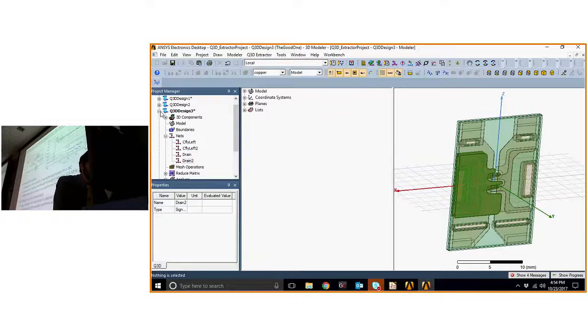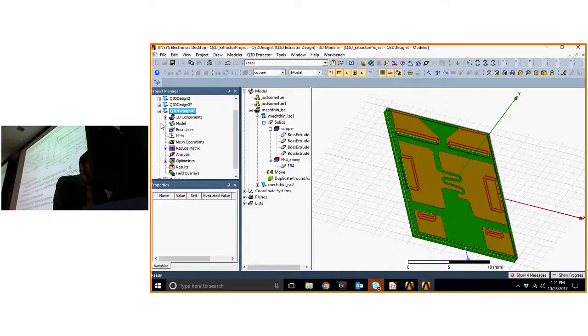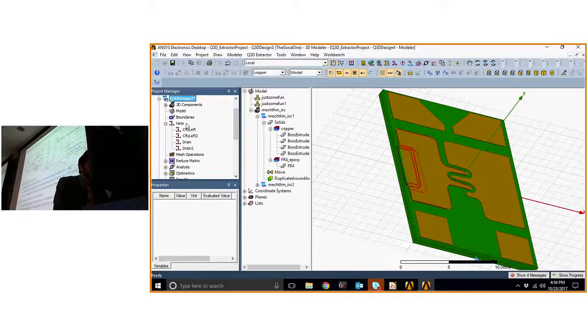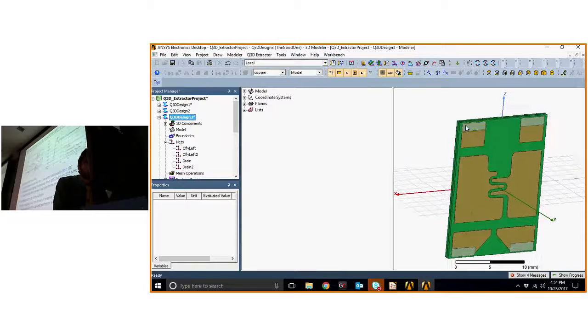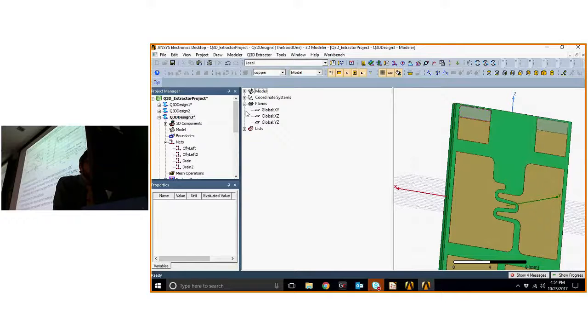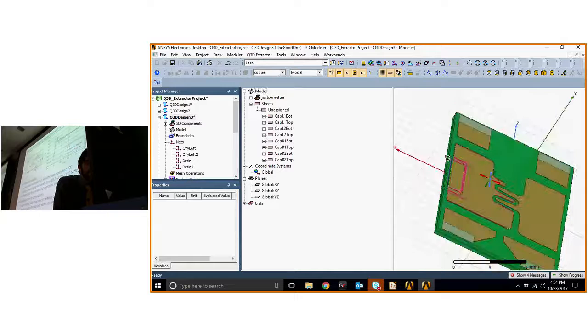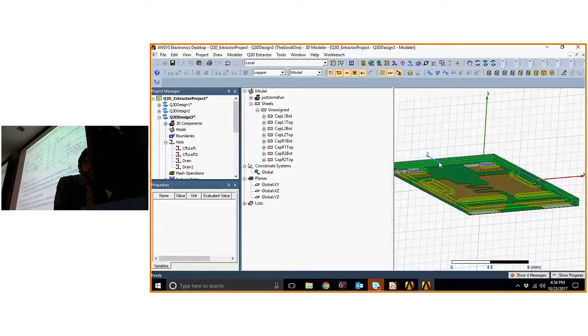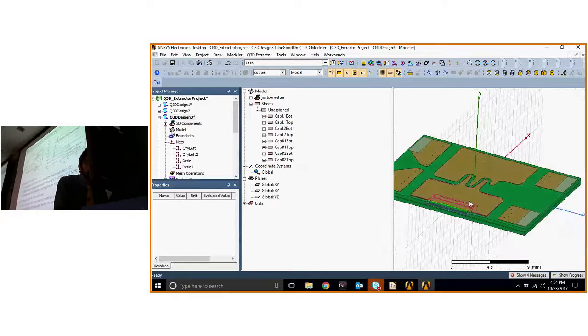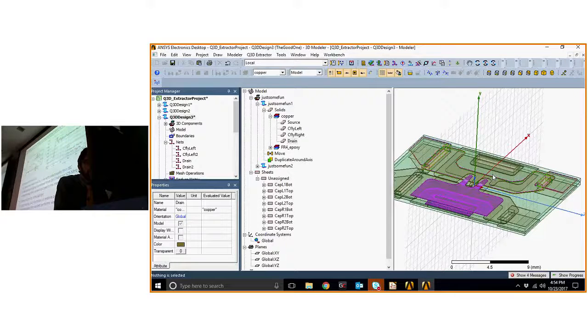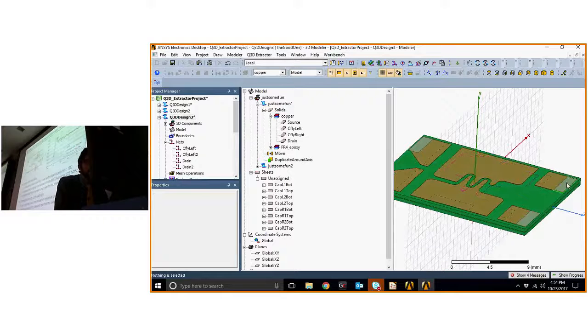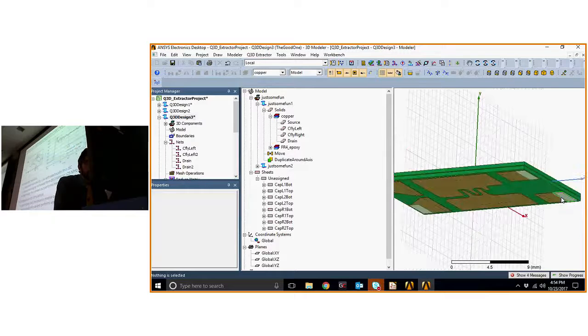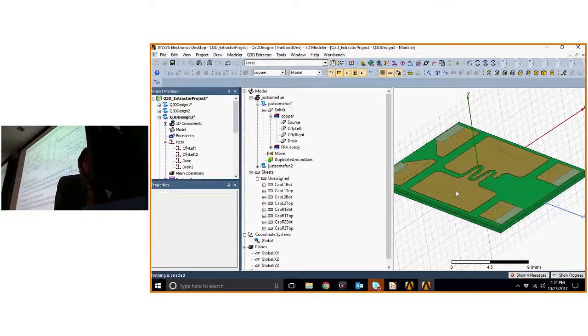In order to actually use them, though, you need to apply pads, essentially, to each of them, which I have done here. And I took the liberty of naming them all, too. So if we're looking at this switching cell, this would be the drain, this would be the source of the top FET, and then these would be pads for the caps on the top, these would be pads for the caps on the bottom, and this is the left side, this is the right side.